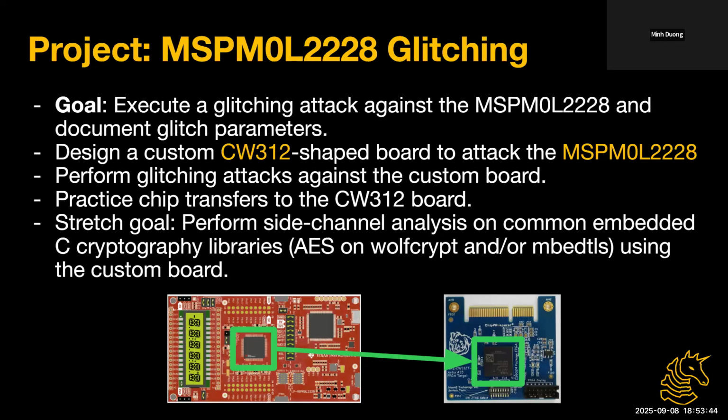If we all use the same set of hardware, then how do you prevent against these hardware attacks? That's a good question. The way it works is the organizers will send us the other teams' firmware, which we flash onto a board that we have. So when we're attacking other teams' designs, we're going to flash their firmware onto our board. The idea is that if we can set up instrumentation on our own board ahead of time, we could just do glitch attacks against every other team.